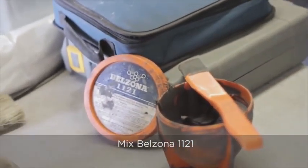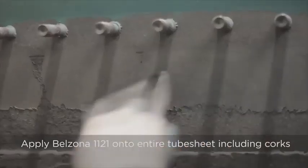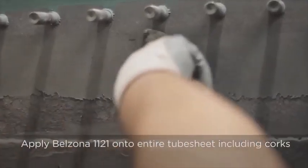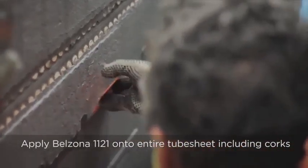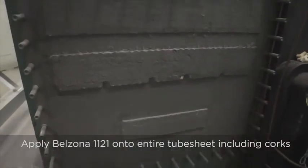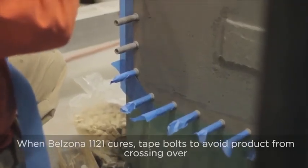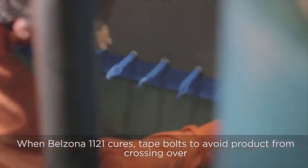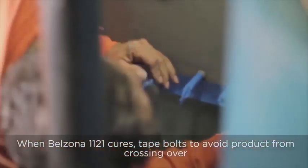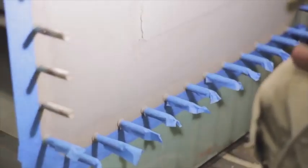In order to get this metal back up to a surface where we can apply a coating, you then mix up the epoxy paste grade, and then he's just going to use a spatula and paste that onto the surface after the surface prep to rebuild it and get a nice flush finish to the application. After the Belzona paste grade is cured, you then remove all of the corks, again to avoid the product